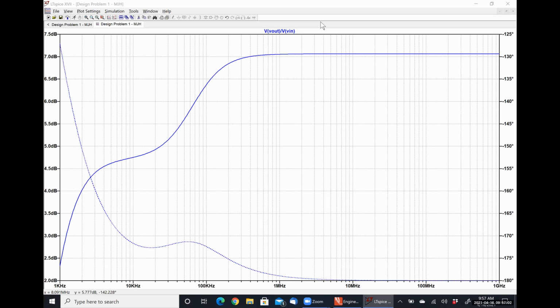And on the right-hand side, after our mid-band, which isn't going to show up on this because it's using an ideal MOSFET, but you guys observed in your electric files with the parasitic resistances, this fell off rapidly beyond a certain frequency as well. So we only have a mid-band where the voltage gain is exactly what we calculated. Then we have a low frequency band where our coupling capacitors dominate what's going on. And then we have a high frequency band where the internal capacitances of our transistors start dominating everything.